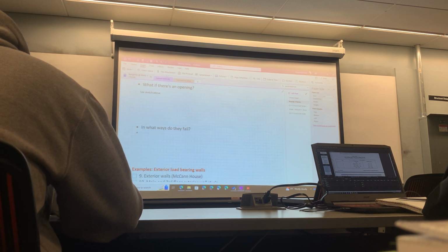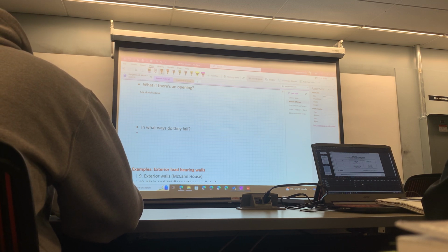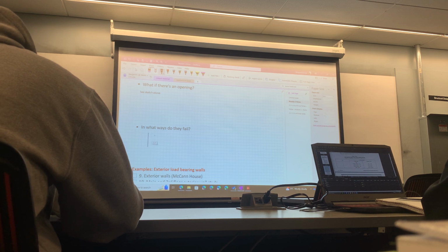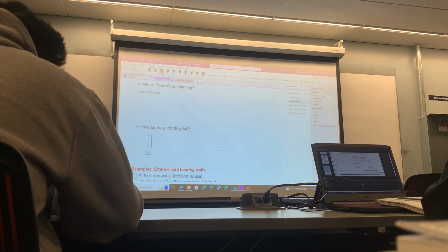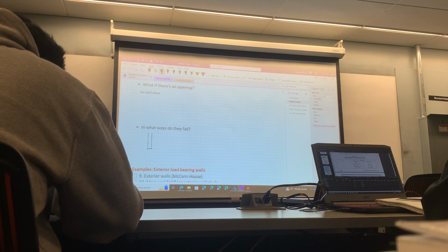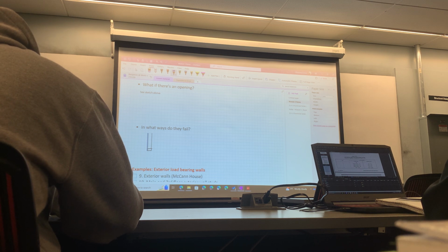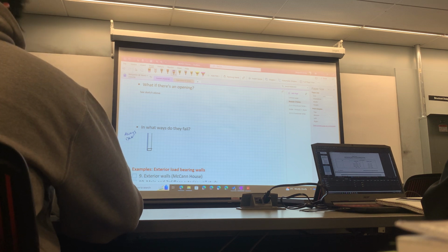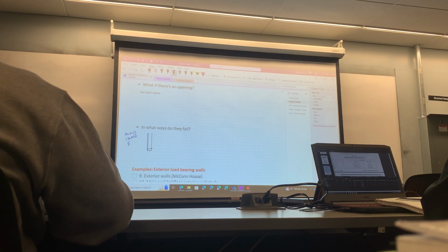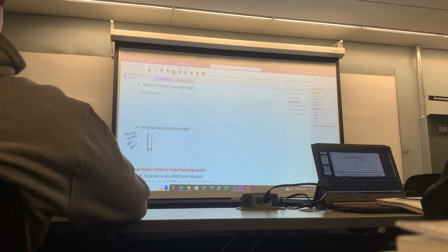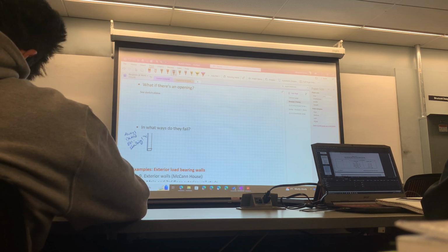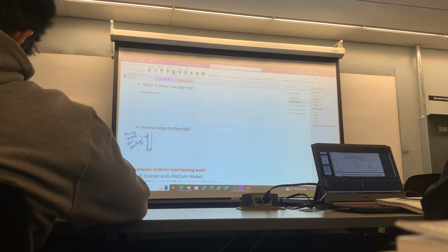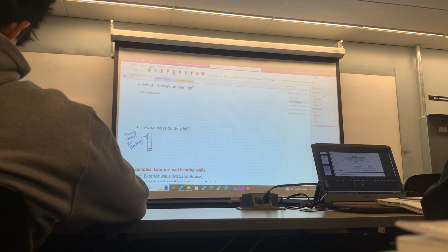Okay, so if we already have we've got our stud here. And we've got our sheathing layer. When you guys draw your exterior studs, always draw exterior sheathing. All right, always draw that line because it's going to be on all the structural drawings.